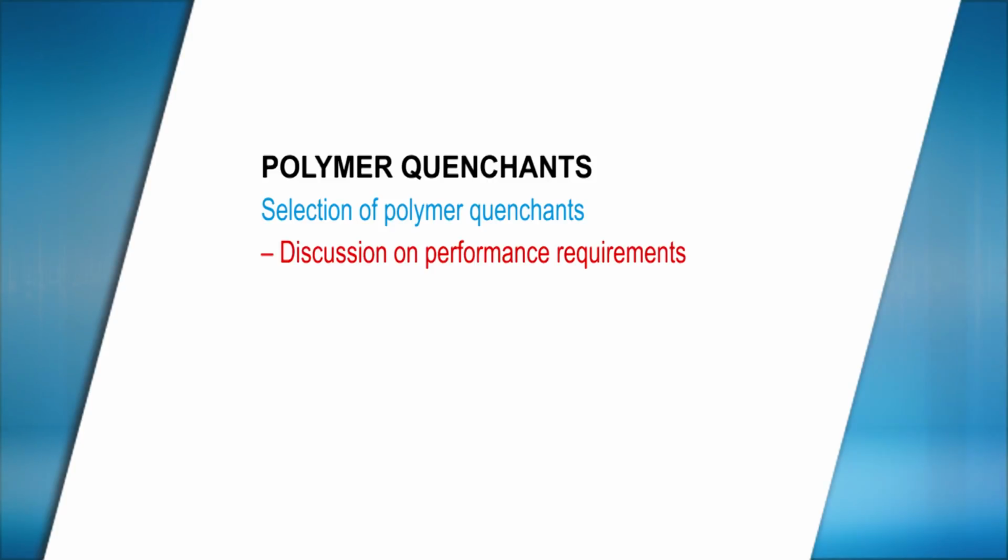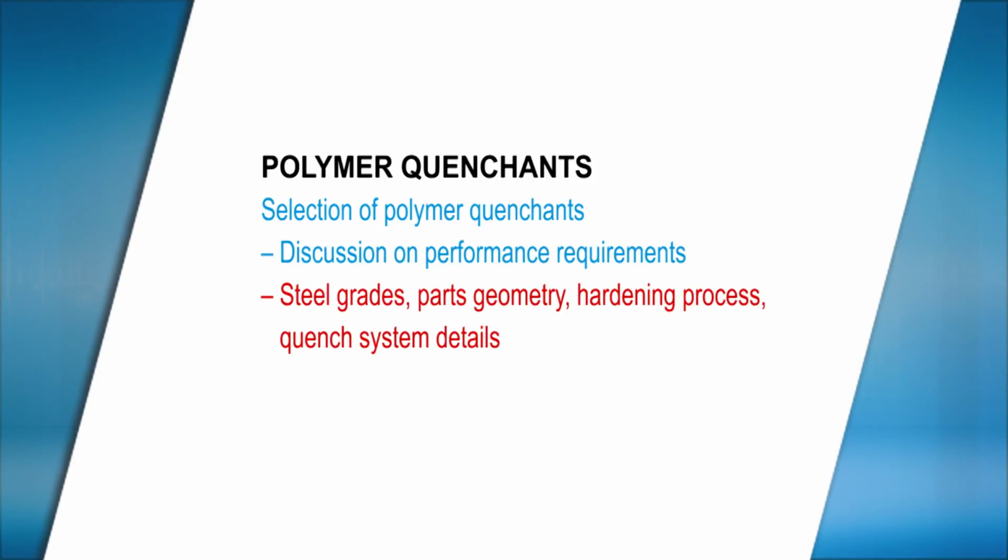Firstly, it is very important to provide the performance requirements of the applications to the technical representative of Hardcastle Petrofer. Secondly, it is also important for the user to provide complete information on steel grades, parts geometry to be quenched, the hardening process used, as well as the quench system. This enables our technical representative, who has extensive field experience, to recommend the most suited polymer quenchant grade.